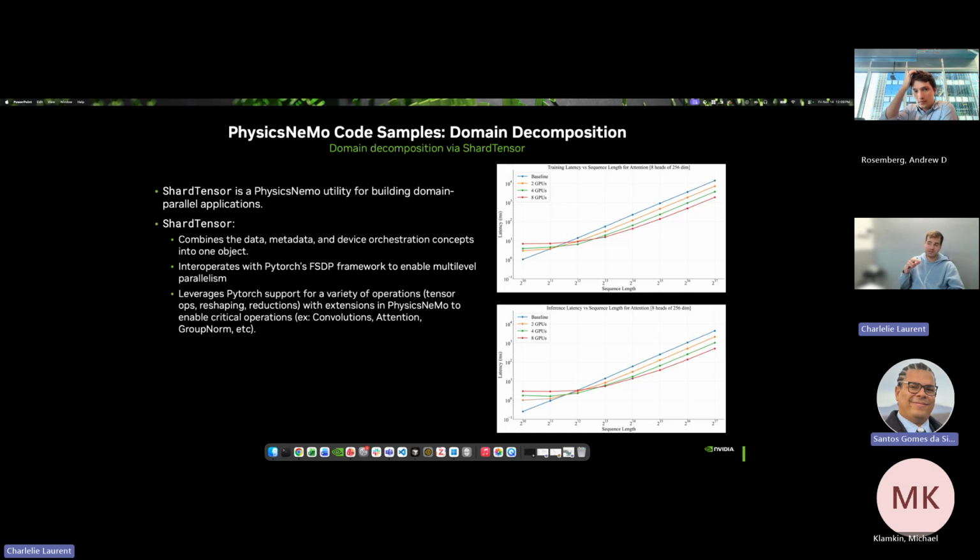So if you have a mesh, it's what is done actually in most traditional solvers. You have your input mesh. There will be a library like Metis or something that's going to shard your mesh and put different parts of the mesh on different processors. So you actually need the same type of parallelism to train AI surrogates. You need to take the input domain, the input mesh, or all the input fields, and shard them across different processors. So it's a very different thing from traditional parallelism used for LLMs.